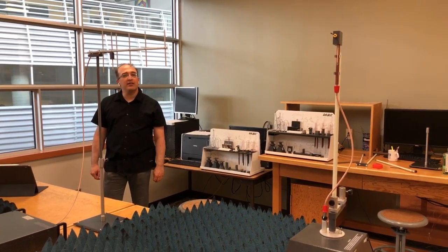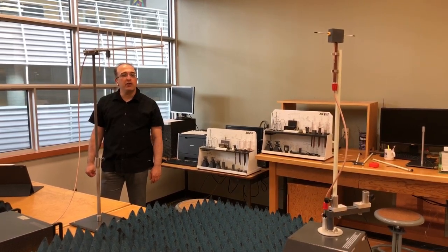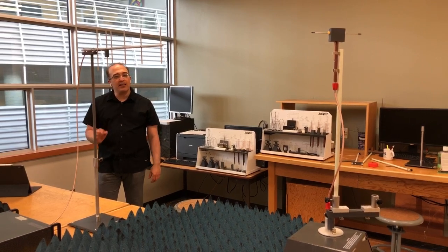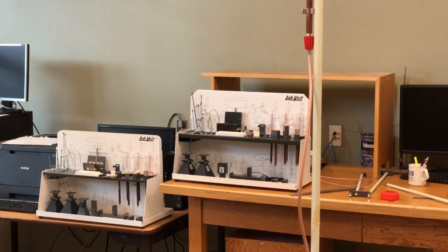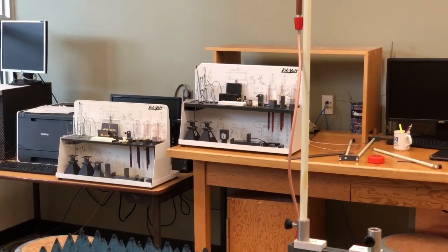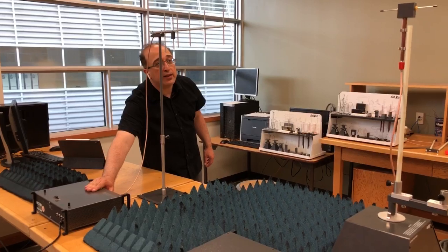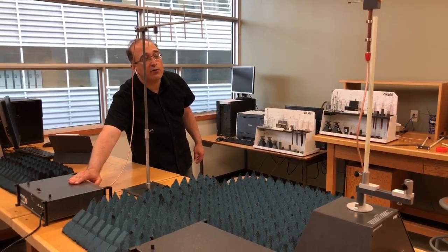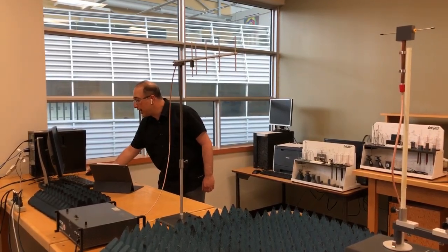Something to note here is that we're going to have the effect of the cable too, because if you look at the cable structure of the receiving antenna, we might pick up signal due to the cable itself, because the cable is now almost in parallel with the transmitting antenna. So that's an issue, and that's part of the reason that sometimes cross-pole might be bigger than expected. Now I'm going to turn off the signal, and then we can take a look at the pattern.